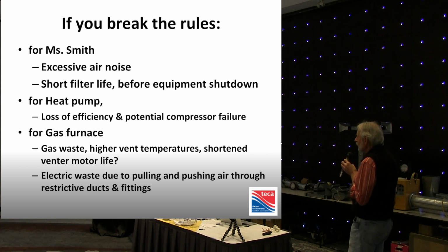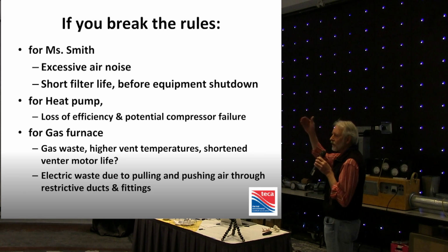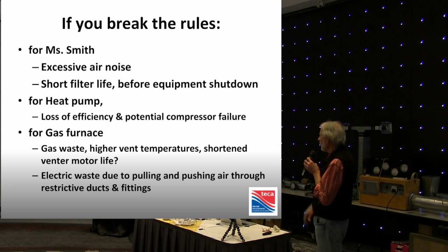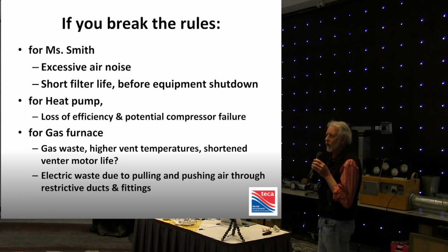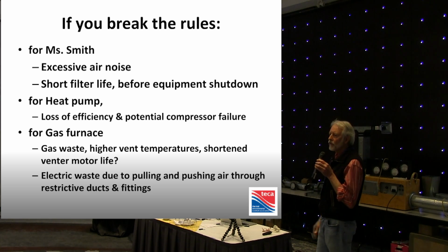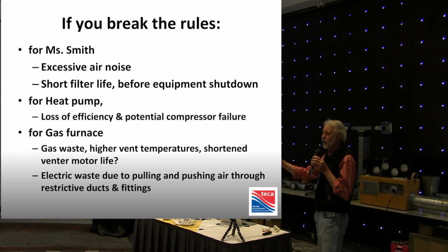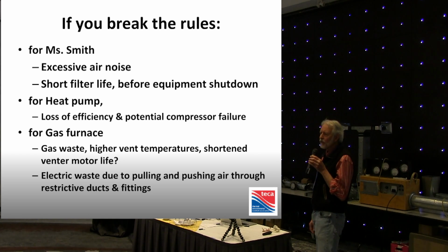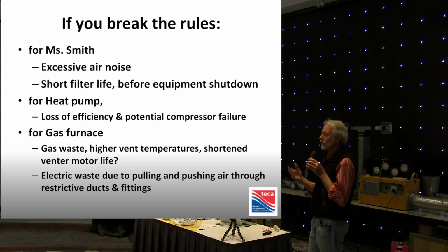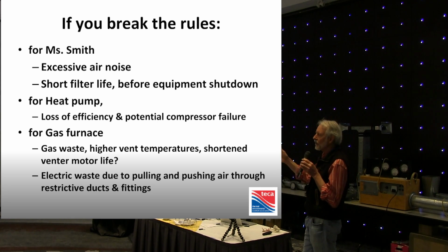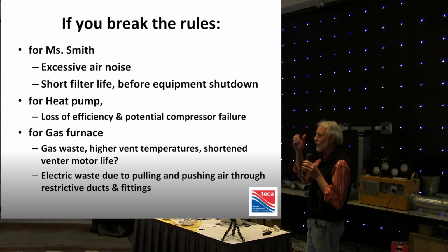In a gas furnace, if we starve them, we tend to have a higher exhaust temperature, which means we cook the venter motor prematurely. And what you may not understand, because our industry has been sold the be-all and end-all of efficient gas furnaces, is to put in the $1,000 electronic motor, and they're beautiful. In fact, GE's patents just ran out recently, but they had the market for 17 years producing what we call ECMs, and they're extremely energy efficient.